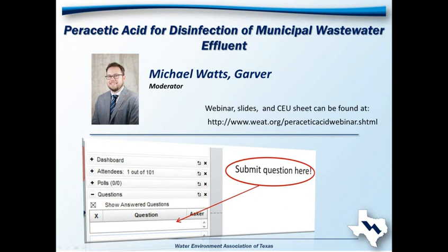Okay, our second question is regarding the facility in Arkansas. Why wasn't tertiary treatment considered prior to UV? Shouldn't that have helped? Great question. I think tertiary treatment would definitely have helped in terms of reducing the fecal coliform bacteria load on the UV, and I think that facilities that use tertiary filters in front of UV do see that benefit.